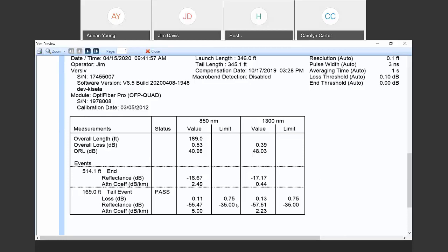Right. Okay. Well, we're getting a lot of questions today. I think OTDRs are a great topic. Here's one of the other ones: what will happen to the loss measurement if you have two different fiber types spliced together? Okay, the loss is the loss. Now, what two fiber types are you talking about? If you splice multimode and single mode, not good. If you splice 50 and 62.5, also not good.